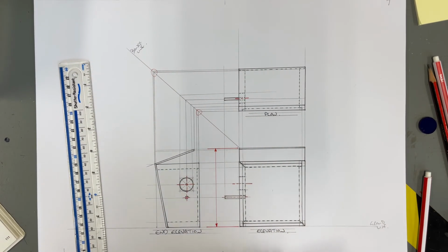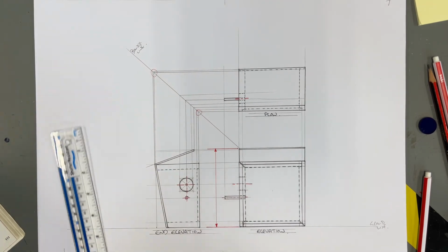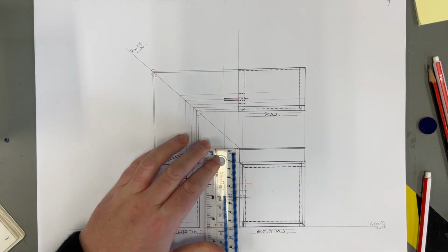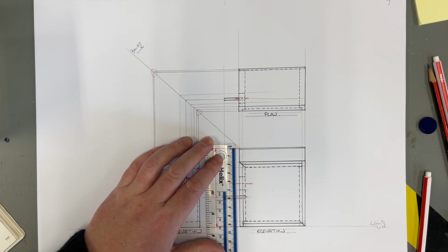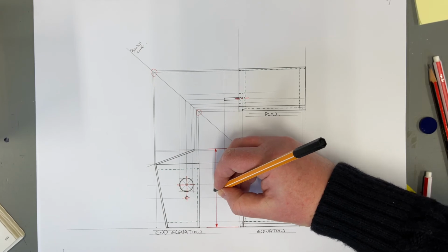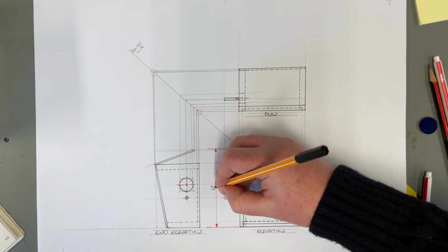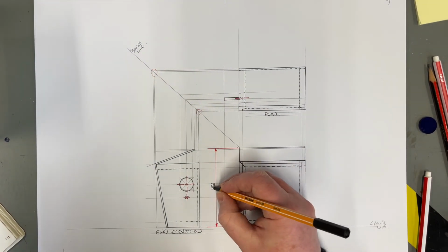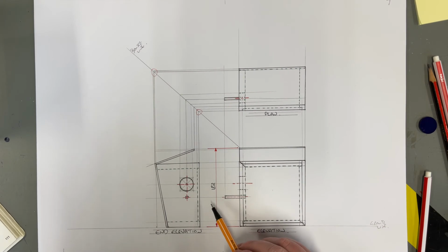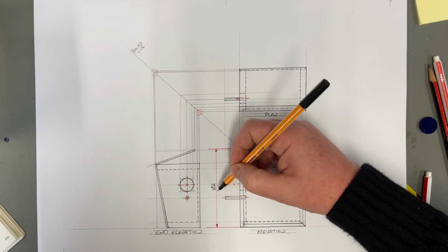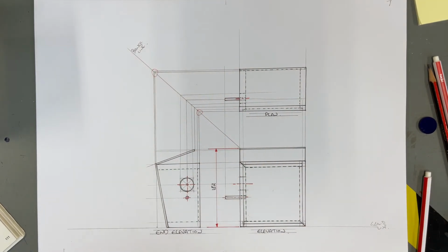Okay, and then our size, which was, let's see, okay, and I drew this at half scale, so I have 91, 182. So you don't scale down your sizes, you always write the sizes in as the product should be made. So in this instance it would be 182 millimeters. We write it, because it's vertical, just remind ourselves, as if we're looking at it from the right hand side. It's then above the line and centred, and you don't put in the mm.